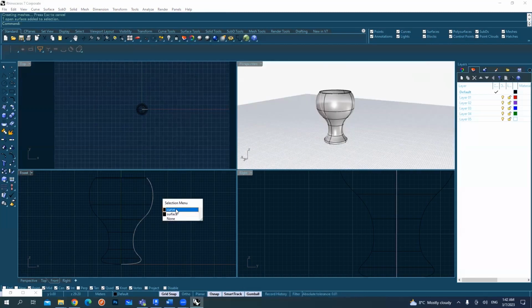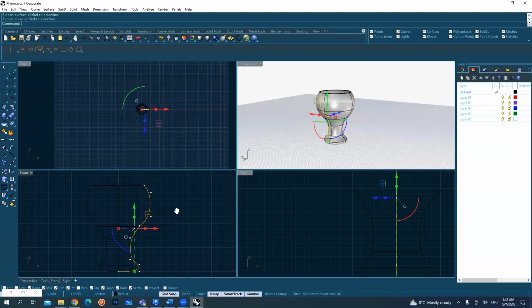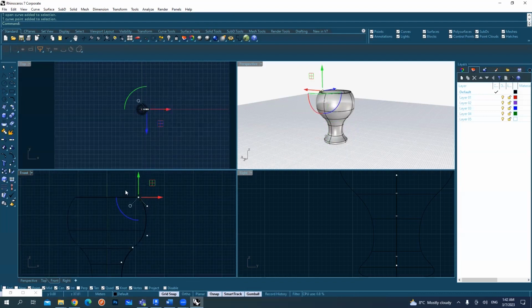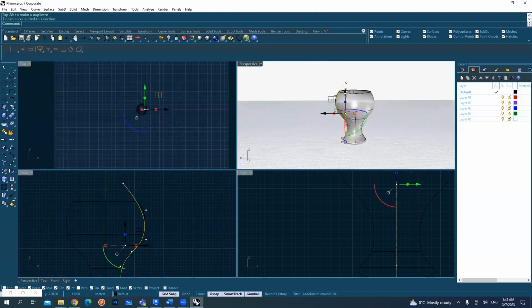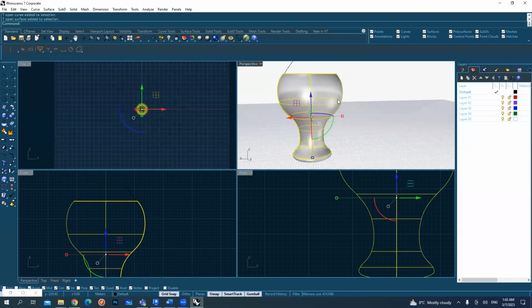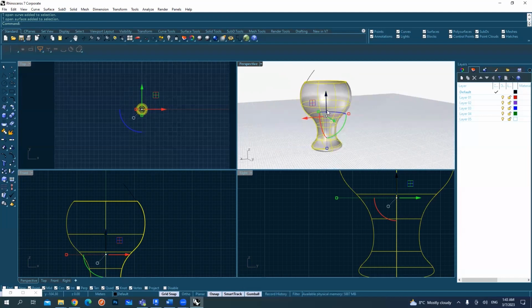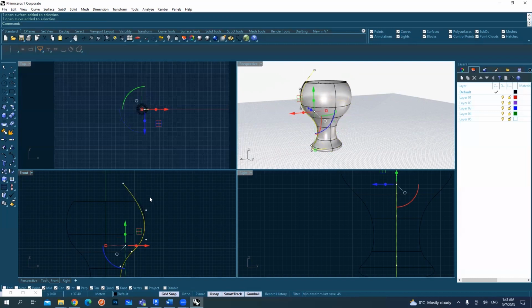This is one problem. I don't like using only Rhino. For example, after I created my revolve here, if I want to move this control point, selecting it from left to right, and change the location of this point, making it shallower or whatever, it only changes the profile, so it doesn't change the surface itself. Why? Because it's Rhino, if you work with it by itself, it's a destructive process. After it applies the command, it forgets everything.